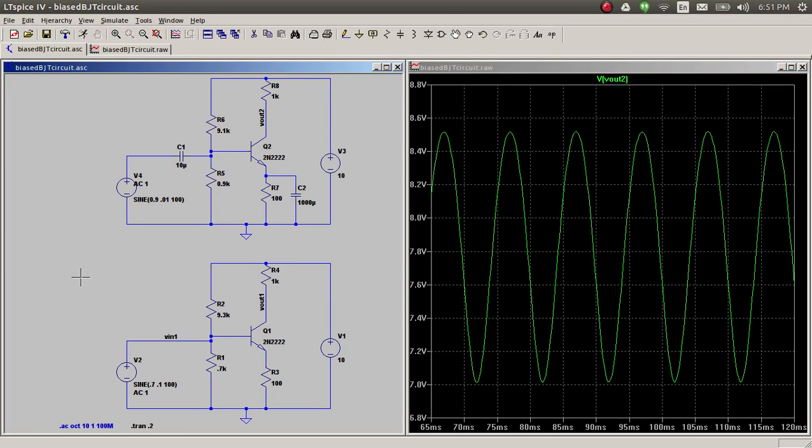So in real circuits, you would not rely on the input bringing the bias that you need. You would set up the bias yourself. You will AC couple the input, and then you will create the amplification that you need. And you can get a significant amplification, as you can see, out of the device, as long as you are careful about the kind of swing you're getting and the kind of output that you need. And that is what the biasing part is. It sets it up in a place where it can do what it needs to do.